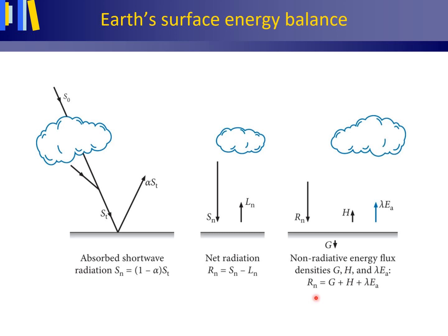This net radiation energy at the surface, Rn, is used for warming the soil below the surface by soil heat transfer, G, warming the air by sensible heat transfer from the Earth's surface, H, voelbaar warmtetransport, and or latent heat transfer, which is evaporation from the Earth's surface, lambda Ia, latente warmtestroom, damping. G, H, and lambda Ia are all expressed in megajoule per square meter and per day, and are assigned a positive value when directed away from the surface.